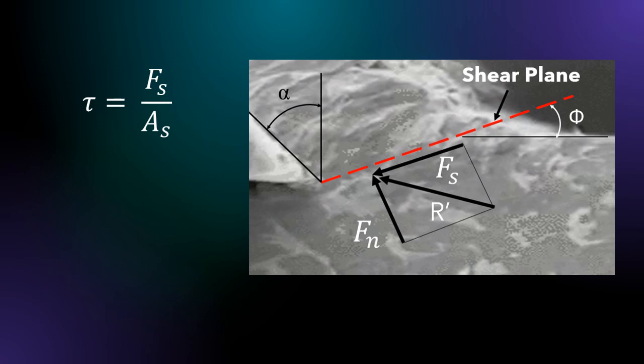The shear stress represents the level of stress required to perform the machining operation. Therefore, this stress is equal to the shear strength of the work material under the conditions at which the cutting occurs. Based on the shear force, we can define the shear stress that acts along the shear plane between the work and the chip, where the area, As, is the area of the shear plane.